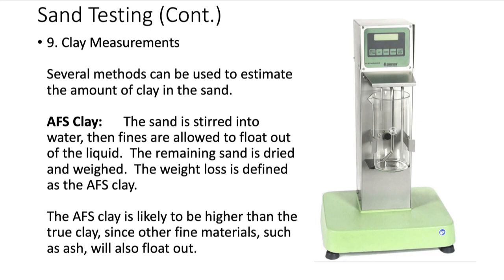The beaker will fill up with water. It'll kind of blast the water around in there a little bit. All the clay, hopefully, will get pushed off the sand grains and be floating in the liquid. We'll let all the sand float to the bottom, but the clay stays in there. And so it just keeps on doing that many, many times. And so all the clay floats out. And some of the other things, too, that throws it off a little bit.